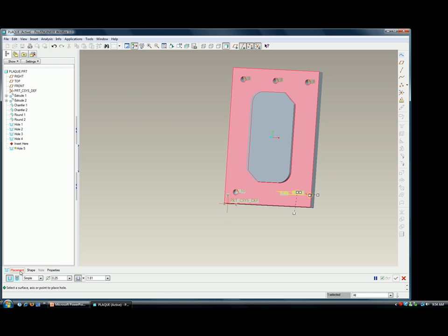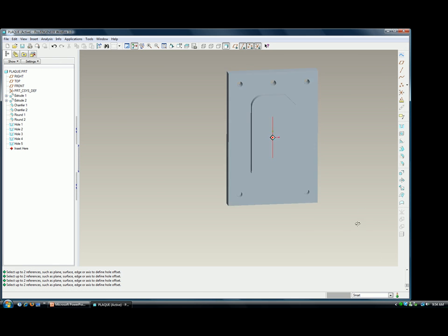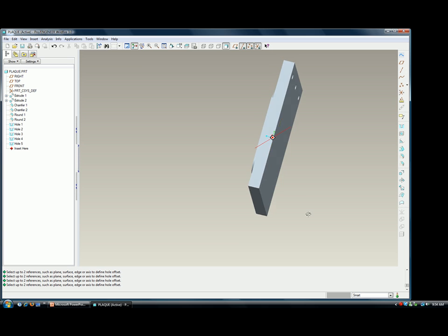placement, click to reference, hold down the Control key, 1 and 2. This will be 1/2 inch. Oops, sorry, 1/2 inch. This again will be 1/2 inch. Okay, 0.25, and the depth I can always change it here too, is actually 0.25. Hit OK. Okay, now we have the hole, the island, the rounded corner, and the chamfered corner.